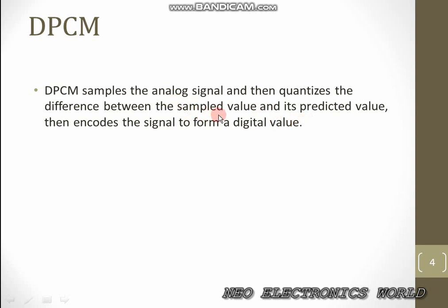Here it's not the sampled value itself, it's the difference that is getting quantized. That's the only difference. In PCM we were quantizing the sample itself. Okay, and at last the process that takes place is the same, that is, encoding.